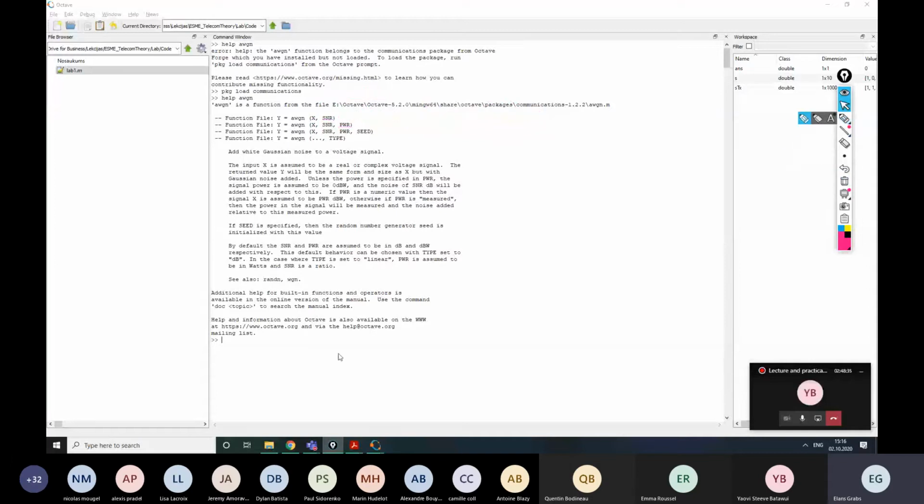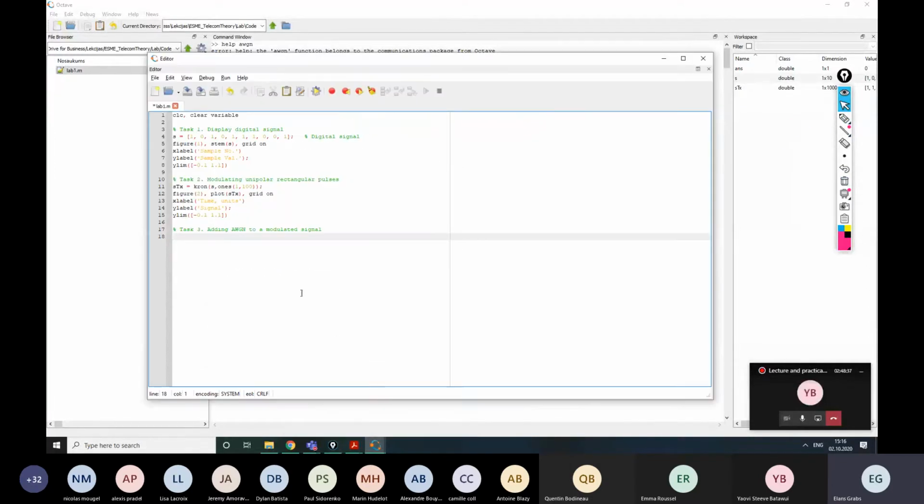We will use it. But before we are going to use it, we need to specify signal to noise ratio. We will specify it initially as 20 decibel, as is asked per our exercise conditions on task. Yes. So this is signal to noise ratio. And then we can create a received signal. This would be signal at the input of a receiver. We are not adding here propagation attenuation.